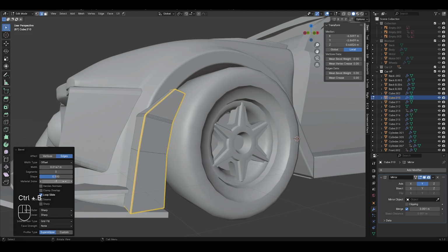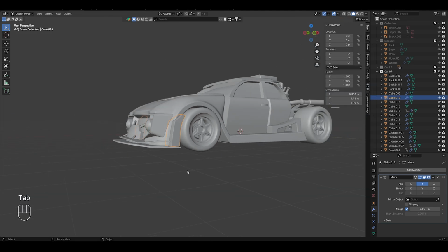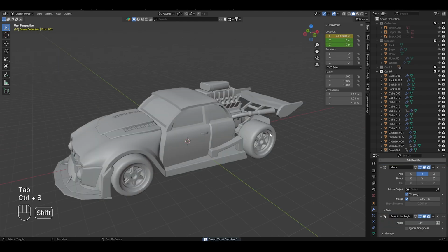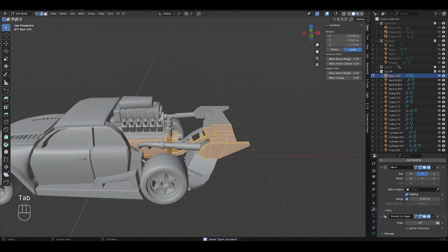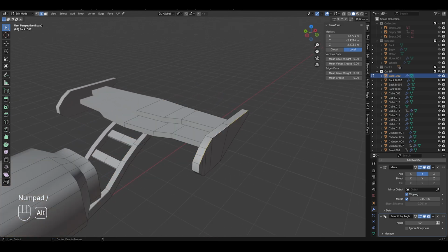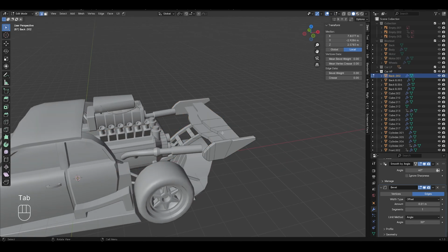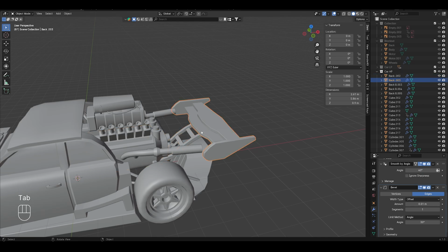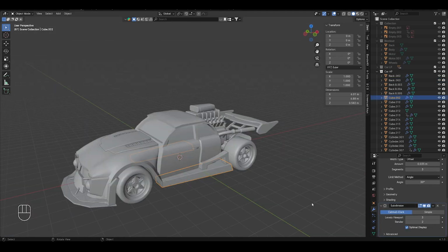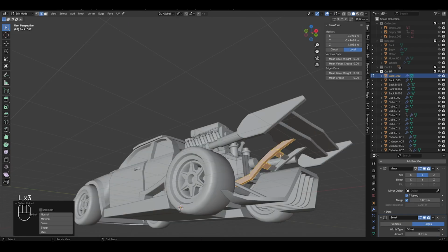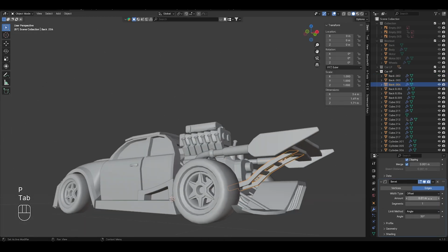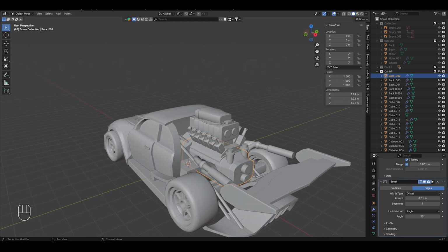And then apply Subdivision Surface. It looks nice so far. Keep working and keep editing the geometry here. I would recommend separating these objects because those are actually different materials and it requires a different bevel on the edges. It does look so much better. Also, remember to remove the auto smooth from the object because it doesn't need it anymore.